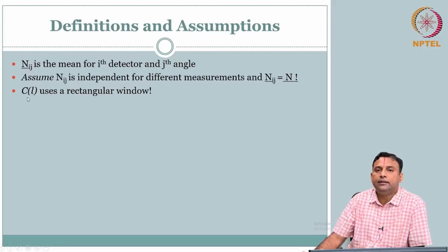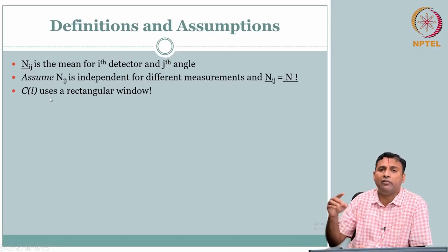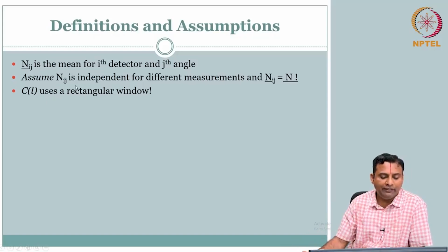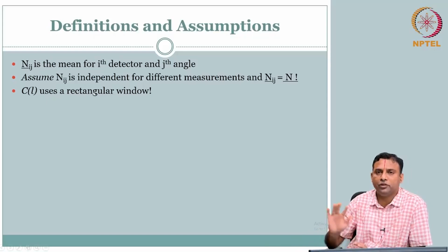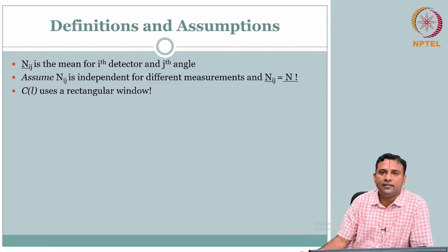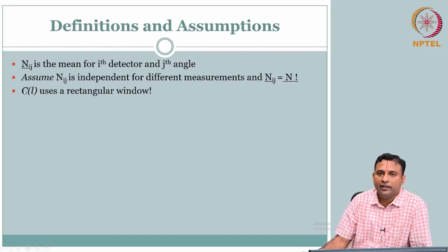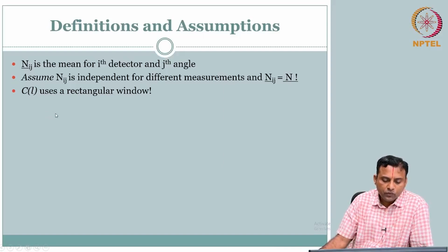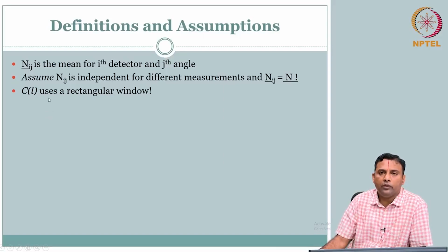Again, CL, this filter function, for simplicity, otherwise you will have to have a Hamming window or Hanning window, you will have to have another exponential or whatever to describe that. To make life easy, we will say this is a rectangular window, so that there is less confusion. But the idea is, you can change this, but for simplicity we will say this is a rectangular window. So this is for the fundamental n that is going in, this is the filter function.